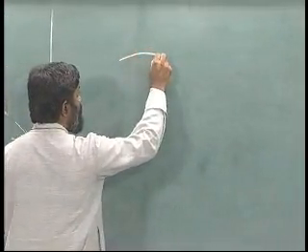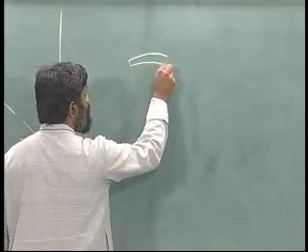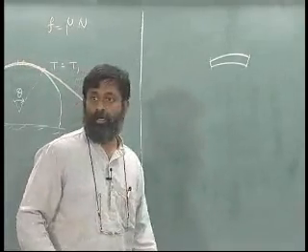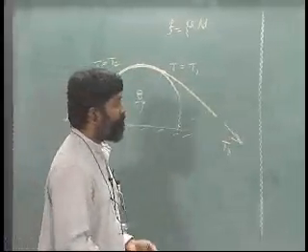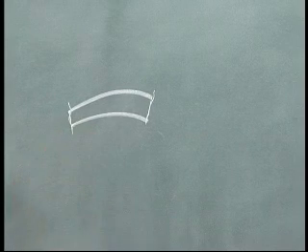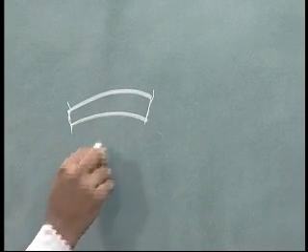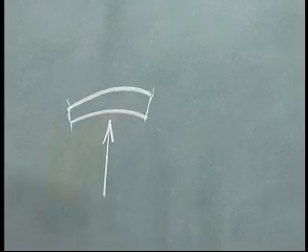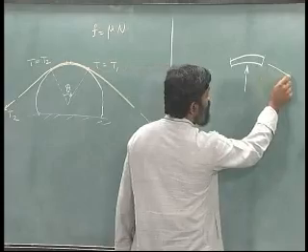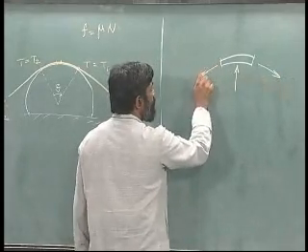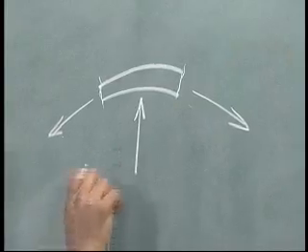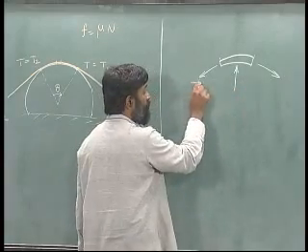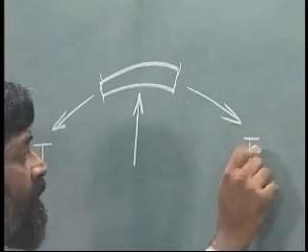So, let us say I am just taking this small belt region that I have shown over here, and I have separated the surface. The moment I separate the surface, there is a normal reaction that acts on it. There is a tension over here and a tension over here. As I move from left to right, the tension keeps on increasing from T2 to T1. So, let us say this is T and this is T plus delta T.